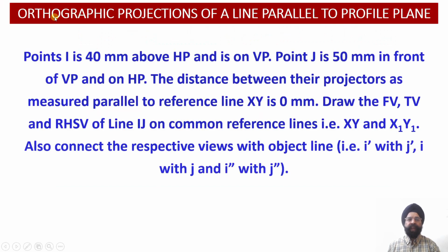So here we are required to evaluate the projections of a line which happens to be parallel to the profile plane. Since this line is parallel to the profile plane, the true length projection of this line onto the profile plane will be obtained, and in the front view as well as in the top view we are going to obtain the apparent length projections of this particular line. So let us go through the statement of this problem.